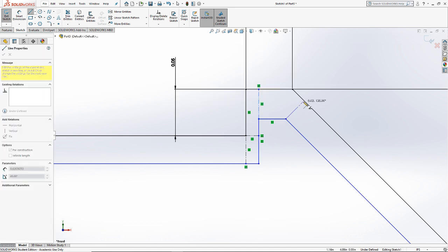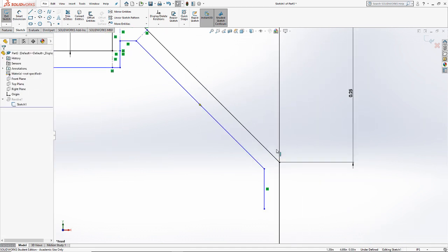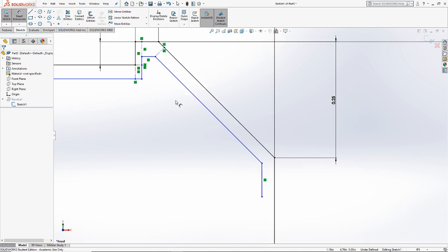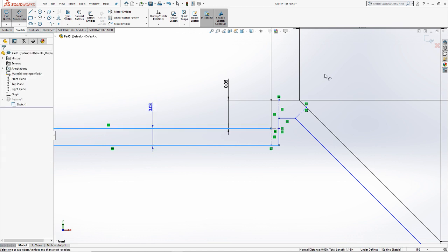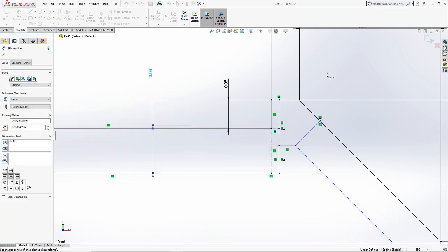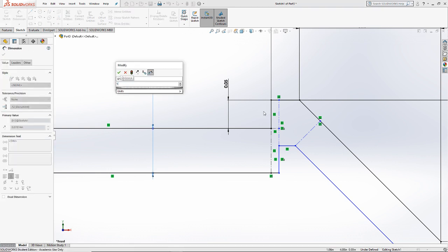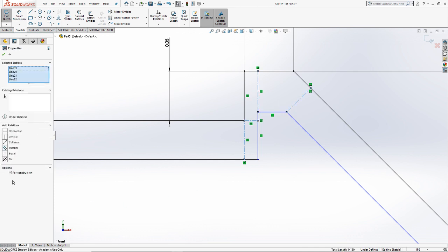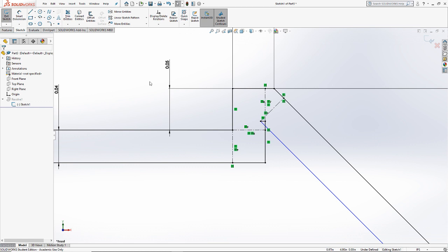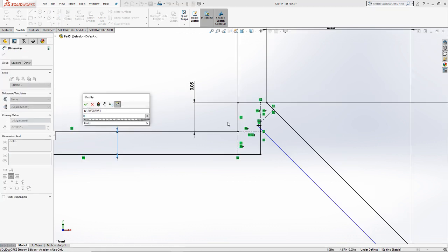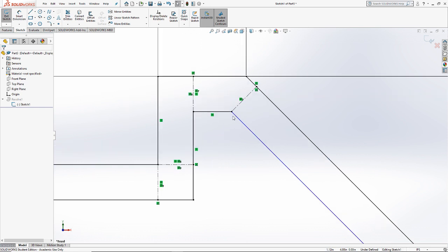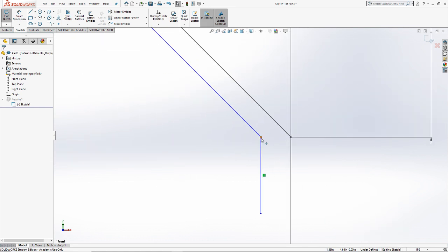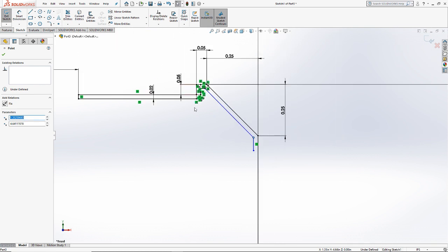And in the worst case scenario, before we show you any sort of shortcuts, we could establish the offset once and then use the construction lines. Like, let's go with 2 millimeters thick. Oh no, that's not representative. 1 millimeter thick, that's much better. Now if I apply the equal relation to all these construction lines, I can see, oh, maybe that's not quite right. Maybe like 0.02 inches. That's much better. Now I could continue on with the construction lines until I have a perfectly defined inside edge of my can. But there's an easier way.